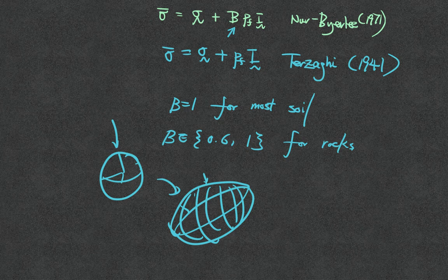So if the b coefficient is not even a scalar, then you will have epsilon_ij plus b_ij times p_f. What it means is that p itself can lead to deviatoric stress or coupling. Usually that won't happen, but let's say I have some metamaterial with a very complex structure. Let me give an example.